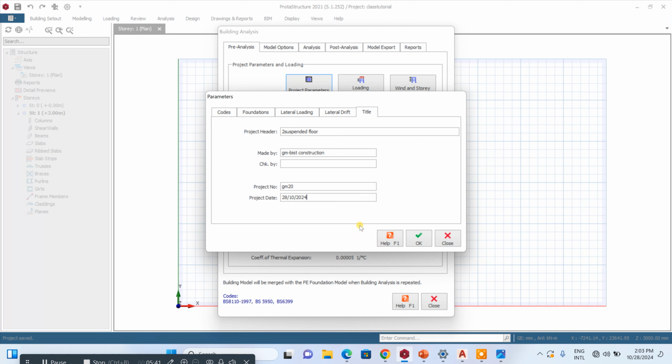Okay, so you know that for every lift there's always an opening, or let me say a door. So we'll have to create our own door here for the lift. I'll just click on it, go to wall opening editor, click on it, then click on add. Then the height of the wall is 2100. Turn this one to 0. So you now have your opening. You now close.